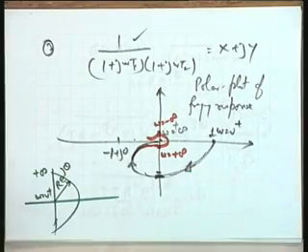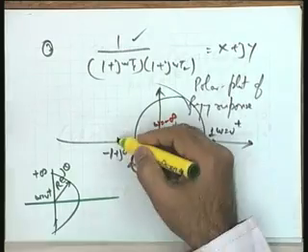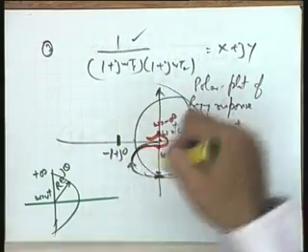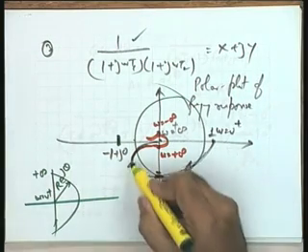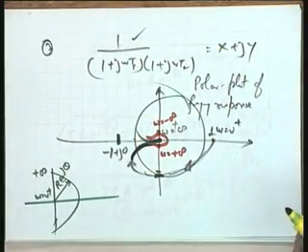But now the question arises, is it not total mathematical jugglery? When I am interested in the minus 1 plus j0 point, whatever shape it may take around the origin, it is not going to concern the stability analysis, and therefore I can just take this into the origin and come out of the origin as far as the Nyquist stability criterion is concerned.